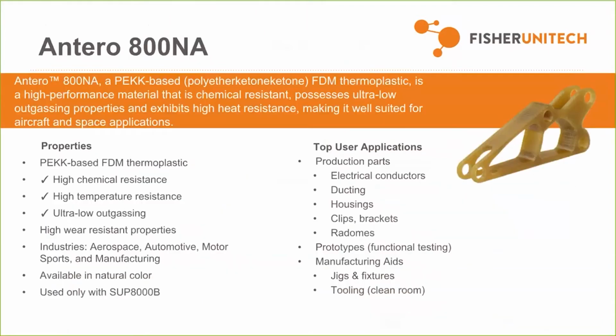The newest material out there right now is called Antero 800NA. It is a PEKK-based material, that's polyether ketone ketone for any of the chemistry folks out there. The three main takeaways here are very high chemical resistance, high temperature resistance, and ultra low outgassing. So if you have any applications requiring those kinds of properties, this may be the material for you. Really great for any clean room applications due to its mentioned low outgassing.